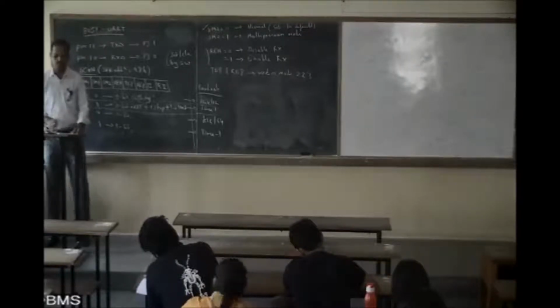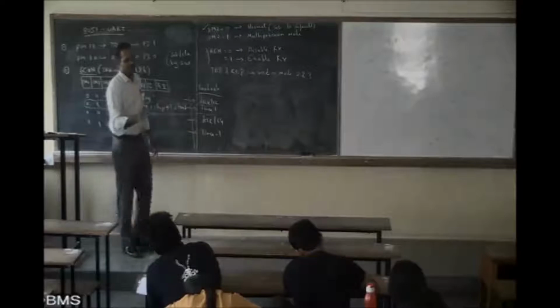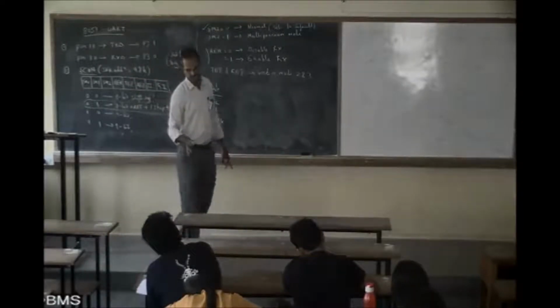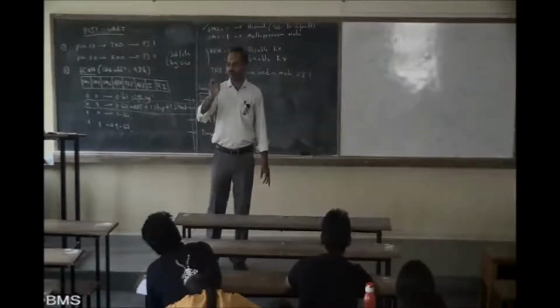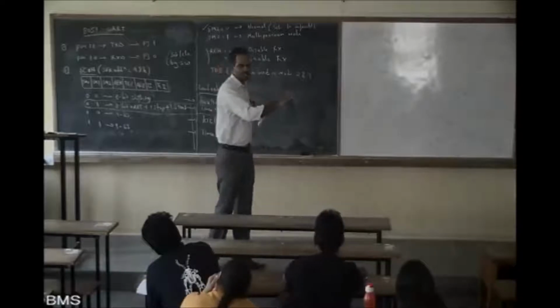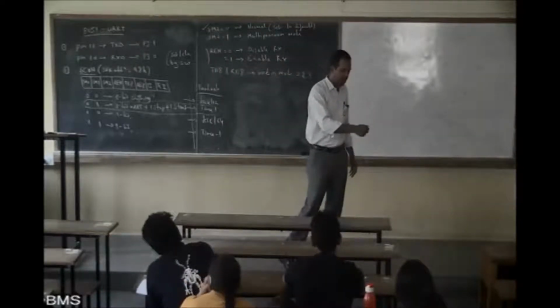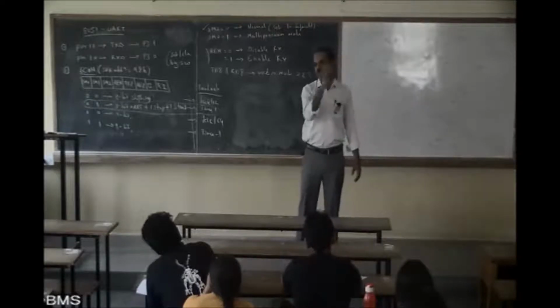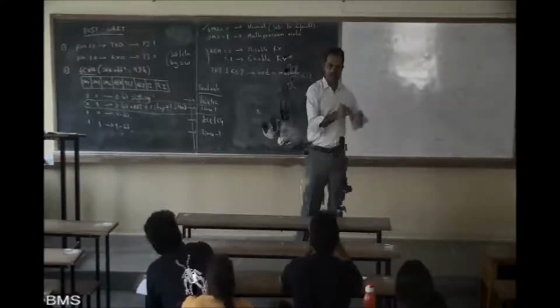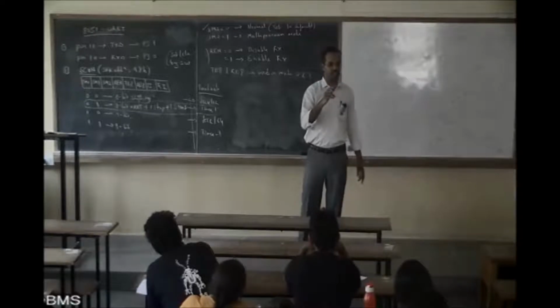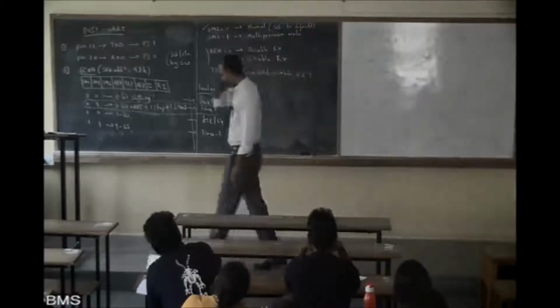You got the point? To summarize, the TI and RI flags will be set when the job is done. Transmission job is there, and when transmission is done, the TI flag will set. Reception job is there, the RI flag will set. Is it clear? Right? Next one.